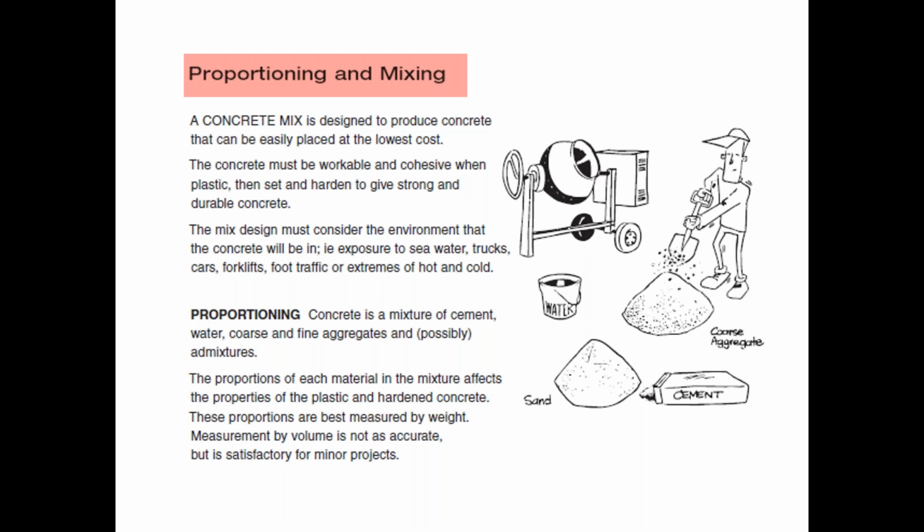Now, proportioning is deciding how much water, how much aggregates, how much cement, etc., etc., that you're going to put into that mix. And again, the concrete technicians work this out for you, but that's why when you're talking to them, you can't just order concrete. They're going to ask you lots of questions. Where's it going? What properties do you want it to have? And they can work with you to help change these properties.